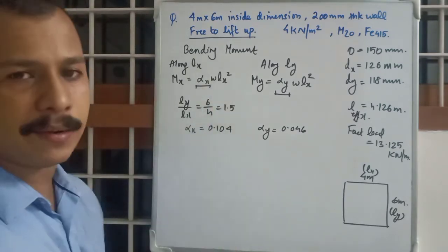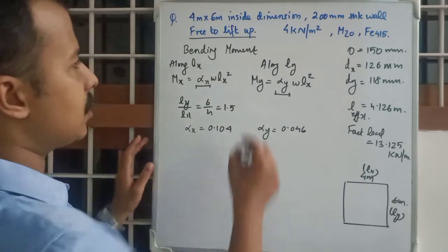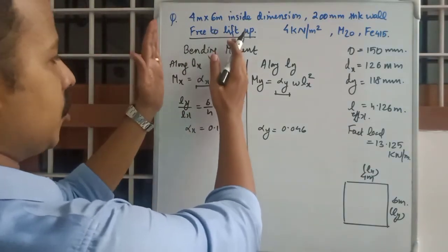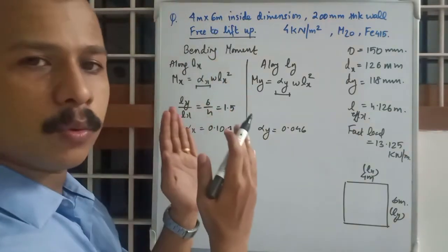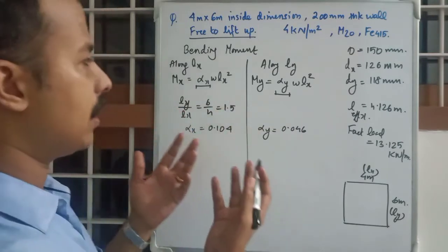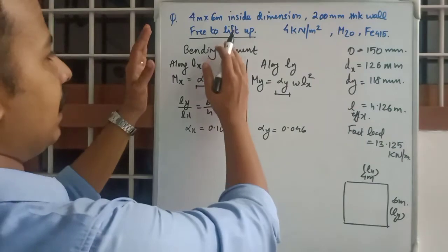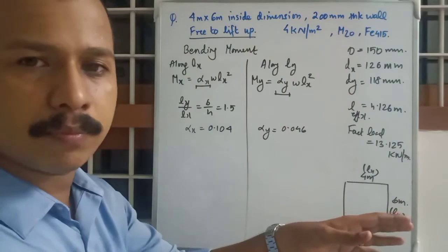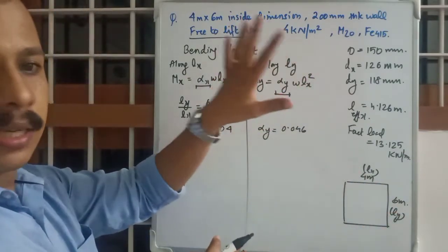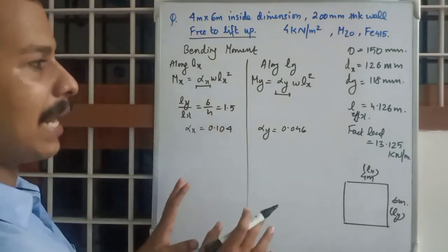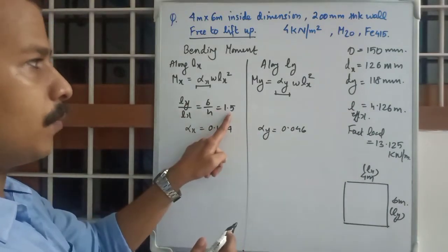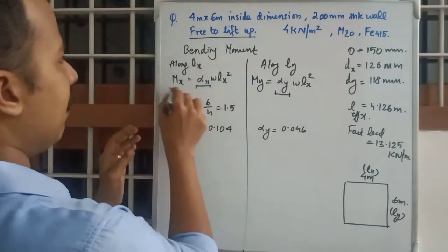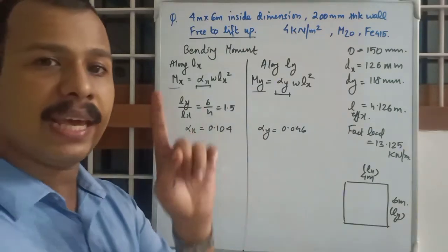Okay, then you can calculate Mx and My. It's just that you will calculate them separately. In one-way slab we calculate only the single shorter span with the Mu that you usually calculate with singly reinforced beams, and then avoid the calculation for Ly and just provide minimum reinforcement as distribution reinforcement in the Ly direction. But in this case, two-way slabs, as this ratio is less than 2, you need to calculate two reinforcements separately. So you need to calculate Mx and My instead of a single Mu.